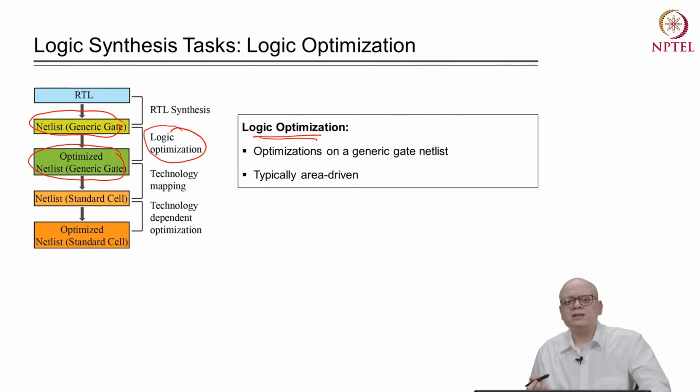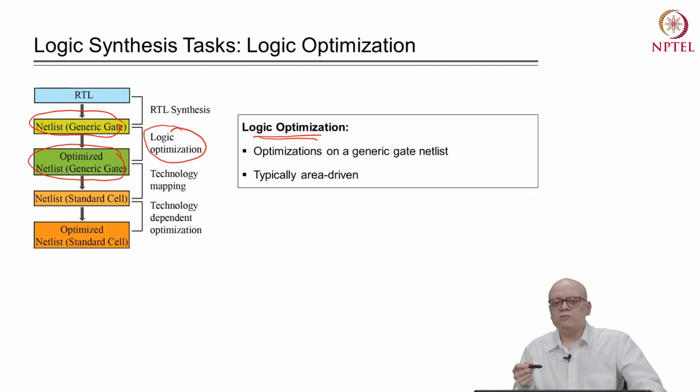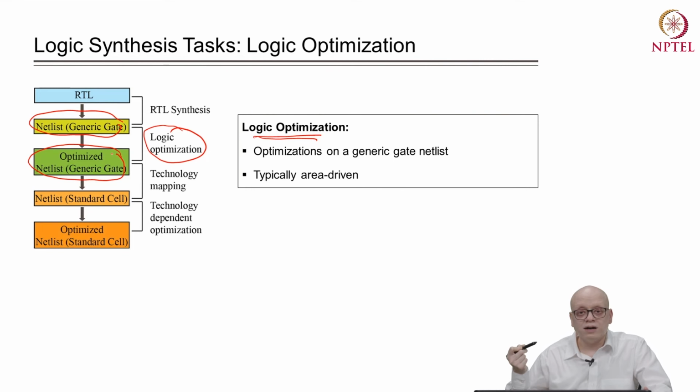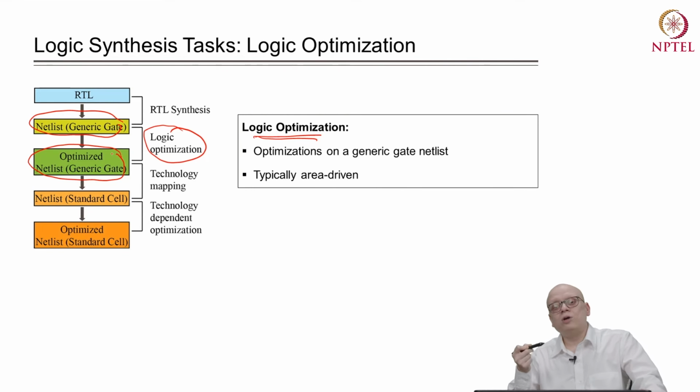Now, what is this logic optimization step? It is similar to the step that you might have studied in your initial courses of digital circuits, where you are given a Boolean function and you are asked to minimize it using, say, Karnaugh maps and so on. When logic optimizations were done in the course of digital circuits, the number of variables treated were, say, 4, or maximum, for the Karnaugh map, you might have gone to 5 variables or so. But if the number of variables increases a lot, for example, it becomes 100, how do we do the optimization?